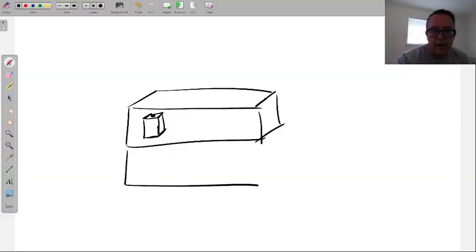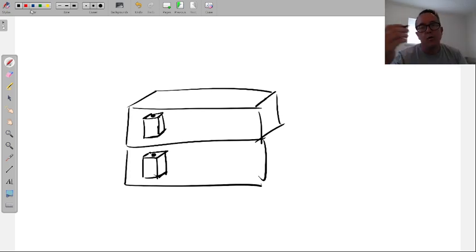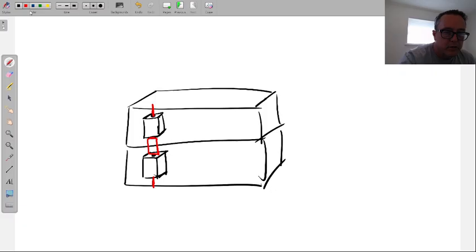If I put two breakers side by side, both having that little hole, then they sell a pin. There is an actual factory pin that goes through here. It has a little square here, goes through the other one, and now I've tied both of these breakers together. You could also do this with a number 12 solid if you don't have this pin, something we do in the field a lot.